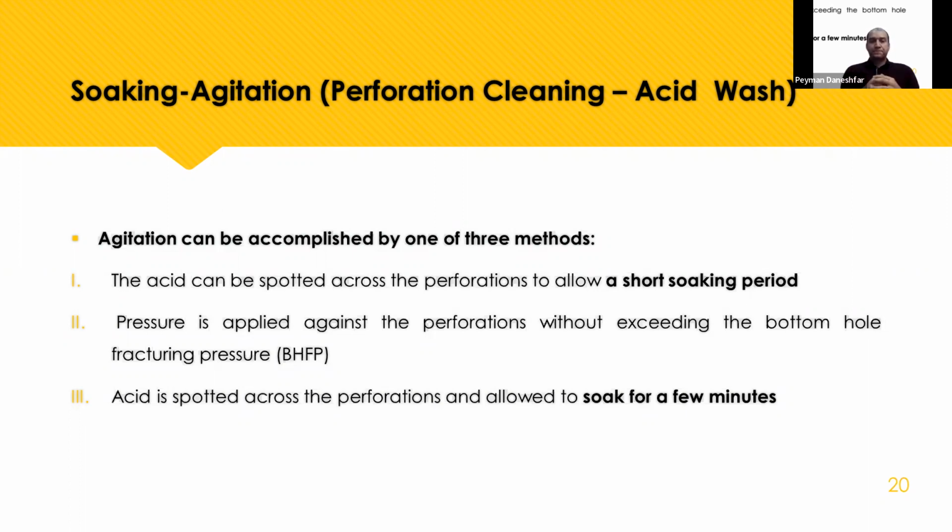We inject the acid into the well, and for a few minutes we wait to see the effect of the acid, and after that we clean. And another one is that we inject the acid below the fracture pressure only for cleaning, and we need the reaction, we need the time. As you can see here, the acid can spot the perforation for a short soaking period, or the pressure is applied against the perforation without exceeding the bottom hole fracture pressure. And another one, we can soak it for some minutes.